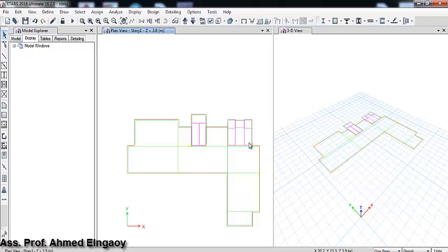So I will draw stairs. And if you need to complete the model, it must begin with the stairs, because if you leave it to the last part, you can't view the points, the slabs, the beams. So you can find some problems choosing and selecting some elements. So the stairs must be done first so you can draw easily.